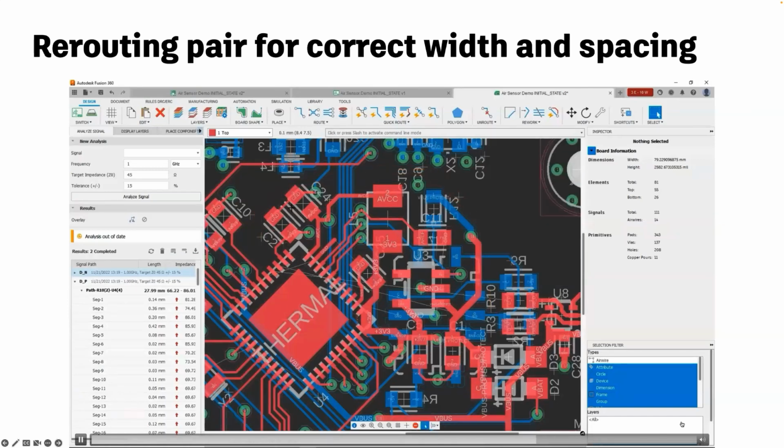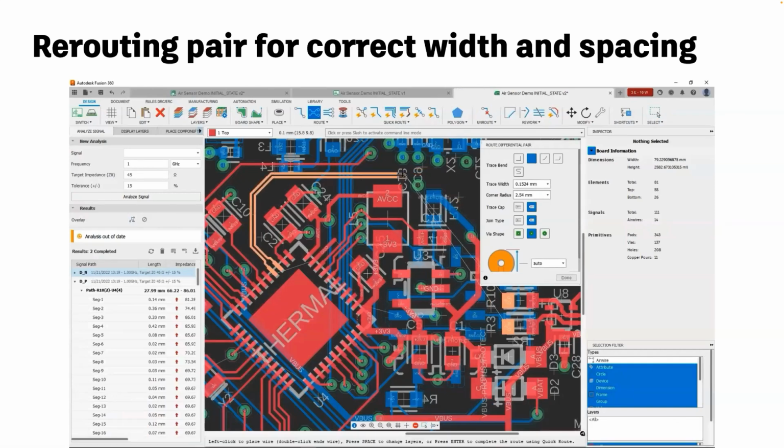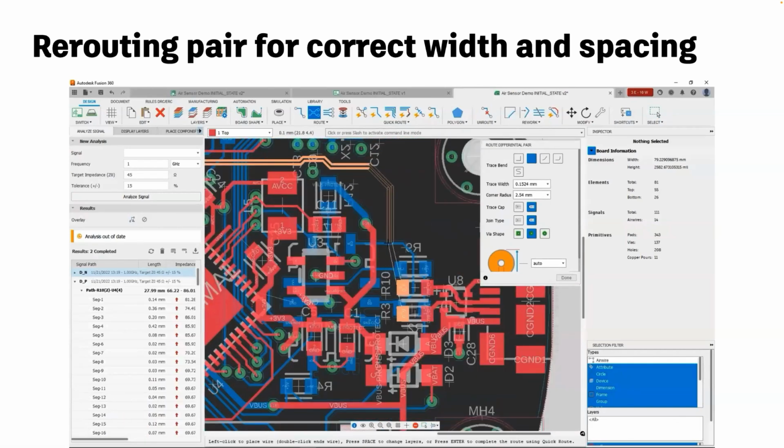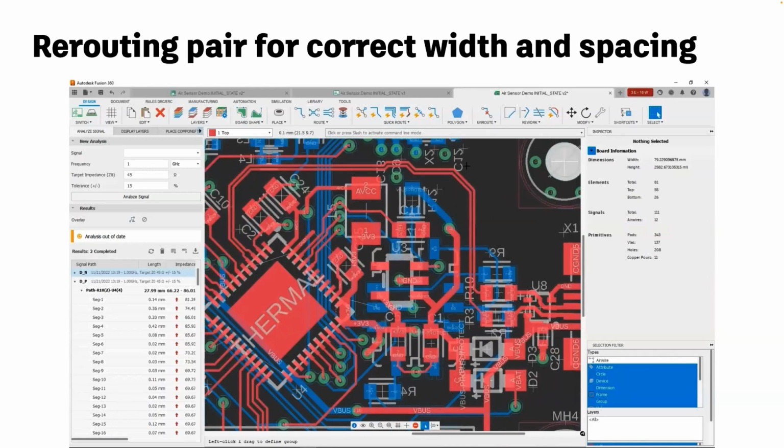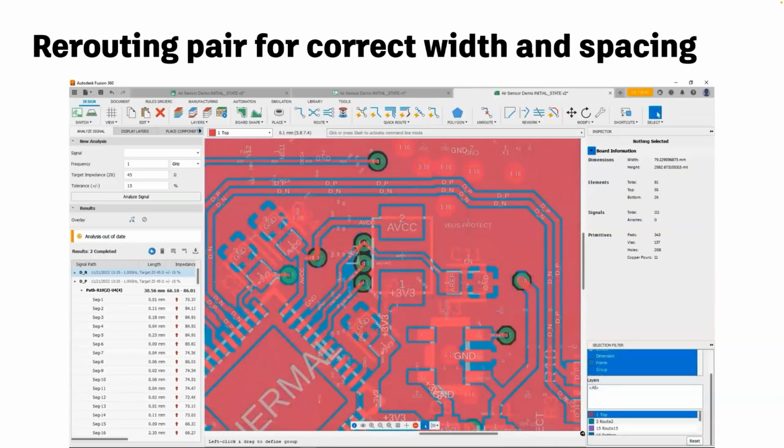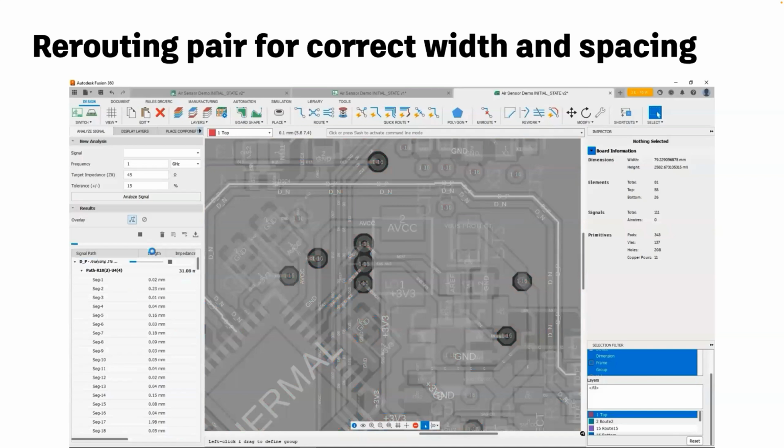And now you're going to see the process of it getting routed. I created some separation from those capacitors because I want to be far enough away that they don't affect my impedance profile. And I get the polygon filled. You see the polygon is filled.